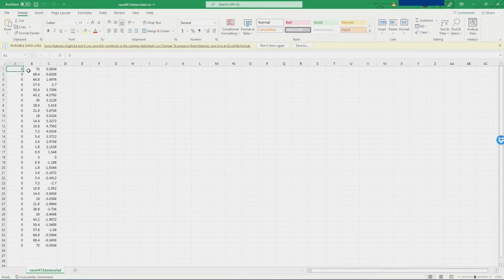There we go. So what I did was I added a column of zeros because for Fusion to import a spline, you need XYZ data. So I just added a column of zeros to essentially create the X data to put it all in one plane.